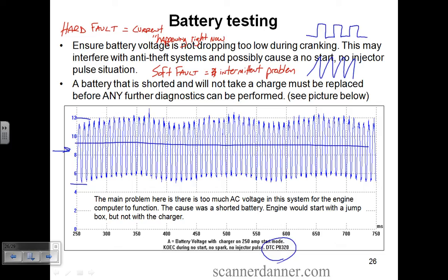You know, and they had already done a new ignition lock and key because of the code, but it keeps setting this anti-theft code. I was able to duplicate it by the second crank. So what I realized in testing the car, here's what I realized. I had the key on, I was doing some voltage checks, and the car died on me within 10 minutes of having the key on. I'm like, well, that's not right.